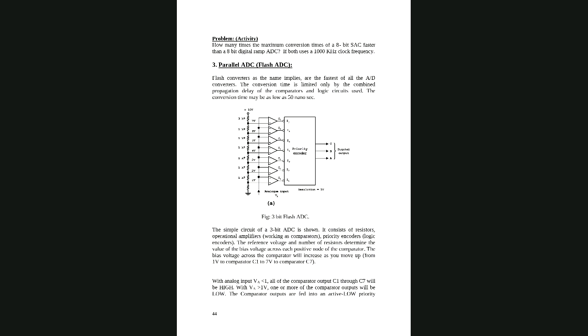But for example, if I tell you at this point, please listen to me, how many resistors are below this point? We consider up to ground. So how many up to ground? How many resistors do we have? 2 resistors, right? Each one is 1 kilo, so total is 2 kilo, over the total resistance in this one, which is 10 kilo, times total voltage. What is the total voltage available? 10 volt. So how much did I get? 2 volt. Simple. Clear?